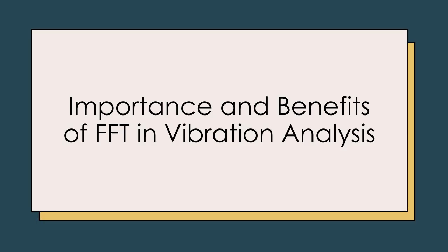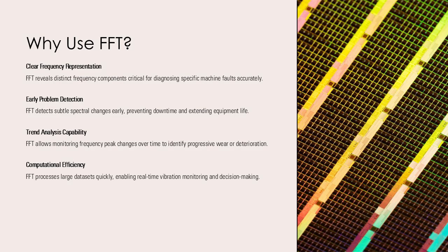Why use FFT? Importance and benefits of FFT in vibration analysis. FFT offers several advantages in vibration analysis, making it the preferred method for frequency domain studies. First, it provides a clear representation of the frequency components present in a vibration signal, which is critical for diagnosing machine faults. Many mechanical issues manifest as distinct frequency patterns, such as imbalance at the fundamental frequency or gear defects at specific harmonics.